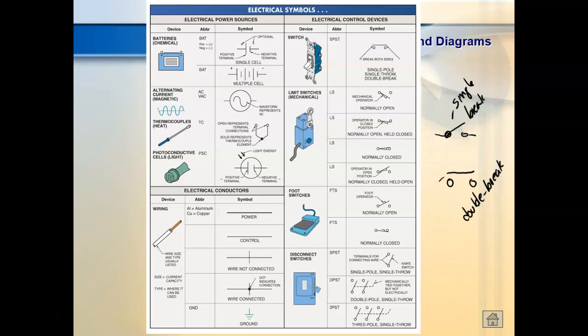So this is a limit switch, and you can actually look in and see when the contacts change. These were given the name because originally they were used just to see when things hit certain limits. We use these a lot now, even to detect when things are at certain positions, but they still have the name limit switch. You can see this one has an operator arm on it, and when something solid strikes it, it knocks it down and causes the contacts inside the limit switch to change states.